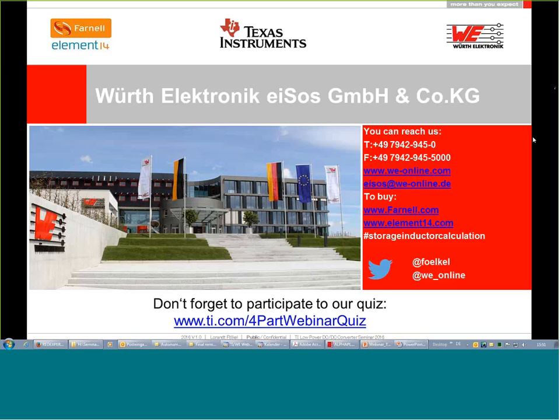Very simple. Somebody asked, could a DC-DC converter be as good as an LDO with a correct design, or would you still use the LDO for a low noise system? Well, of course, a DC-DC converter and an LDO is a big difference. If you talk about efficiency, then the LDO will never be competitive with a DC-DC converter. If you have an RF design and you have very strict requirements for ripple-free current to the RF design, the LDO is the best solution, of course.